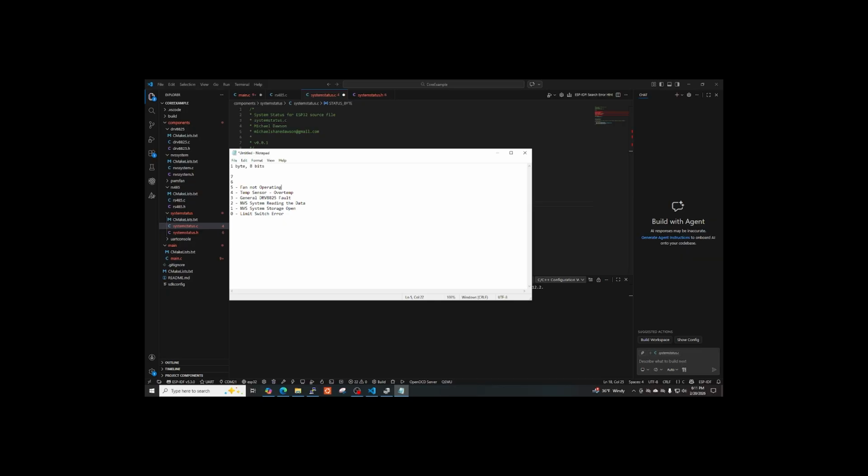If it's supposed to be running and the RPM is not above 0, or let's say above some arbitrary value, that could indicate the fan is not operating, it's stuck, or it's failed, or another subsystem failure, or the fan is not present. We can throw up a fault for it. That can be handled in the temperature driver.